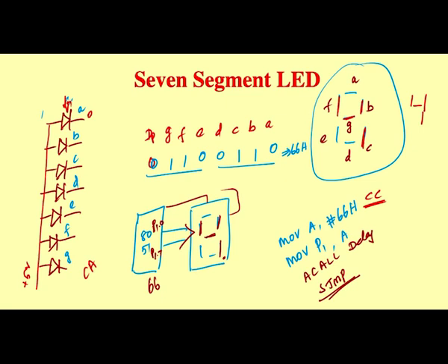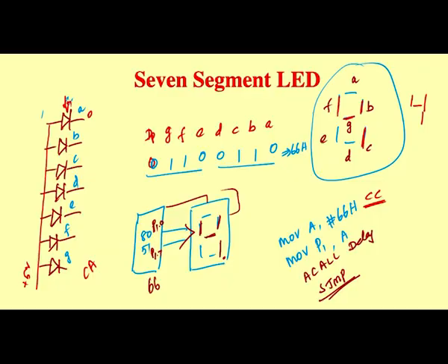So, now how we are writing the program means MOV A, #66H. Okay. Then MOV P1, A. Suppose I am connected with port 1. This is how the connection is available: this is the 8051, which is connected with the 7 segment display. This is the port 1 signal, so port 1.0 to port 1.7, right.